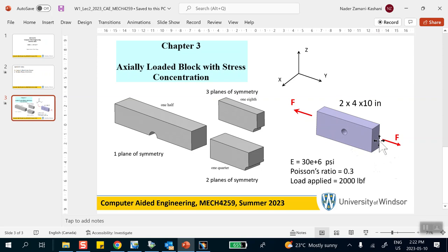Whatever pressure you apply at the ends, the biggest stress on the top and the bottom is going to be 3 times that. That's what stress concentration for a very small hole, uniaxially loaded like that. So we know that there's a big stress variation around this hole on the top and the bottom point.